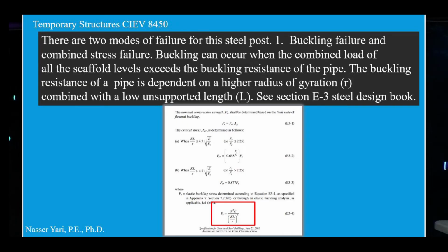One is by buckling, and of course it can be another mode of failure by crushing, but that's not going to happen because buckling controls anyway. So one mode is by buckling failure, and the other mode is with a bending, because our axial force is not quite on a center, which we'll talk about in a minute. But we're going to focus right now on a buckling failure.